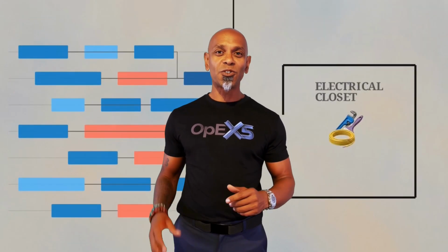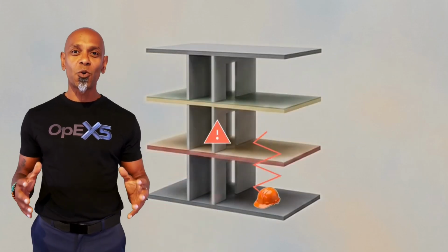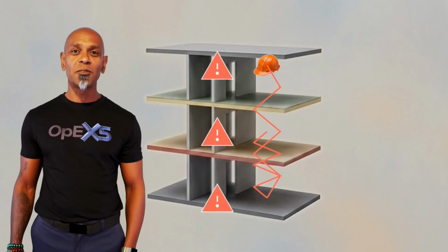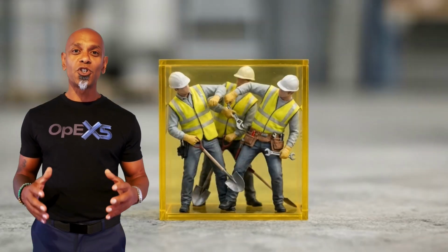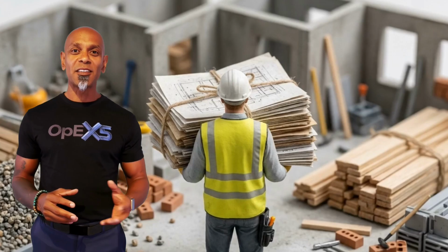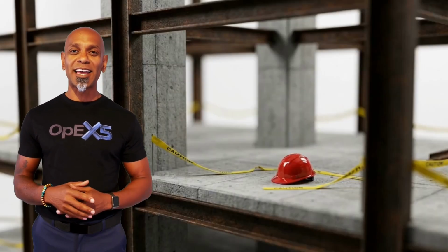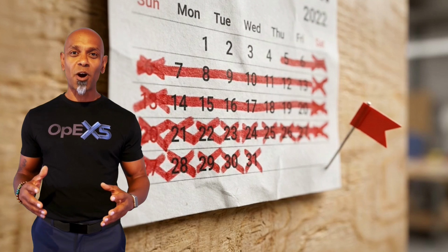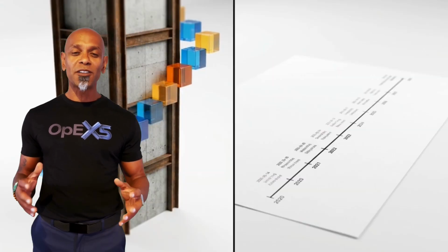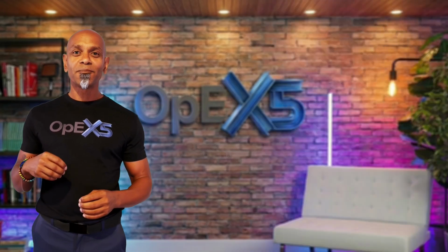Traditional CPM schedules naturally increase work in progress far beyond the actual capacity of your job site resources. It forces crews to jump erratically from zone to zone to hit artificial dates. This results in trade burdening and trade stacking, the primary reasons projects crash land, productivity plummets, and safety hazards skyrocket.